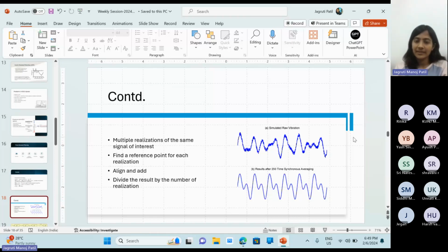In the sampled waveform we get the highest peak, but we won't get the peak which is being added or averaged after considering the noise as well, because here we aren't separating it from the noise. This is actually from the oscilloscope. So we always save this waveform, find the maximum peak of this particular waveform, and then process it further.